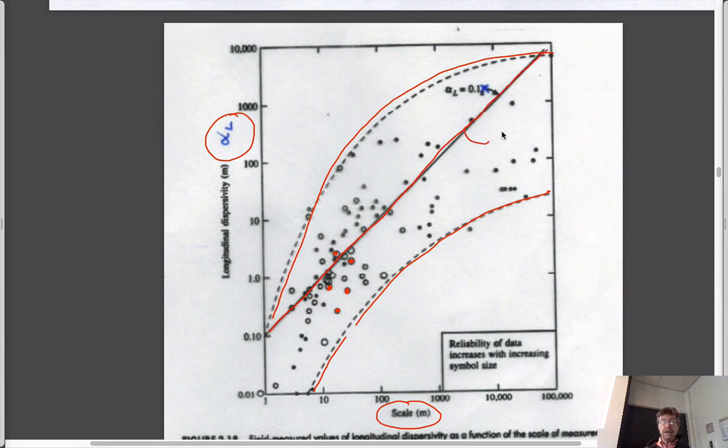The equation of this best fit line is, I'll just write it out, is L over 10. And so this is the length of the plume. And this is just 10. This is the equation of this line. And it has dimensions. This is a length dimension. This has units of length as well, this longitudinal dispersivity. And so the reason that we looked at a value of 1 over 10 on that previous slide was because the actual field data, if you look at them, completely independent of any kind of hydrogeological properties, you could get an estimate of what this value is just by doing that.